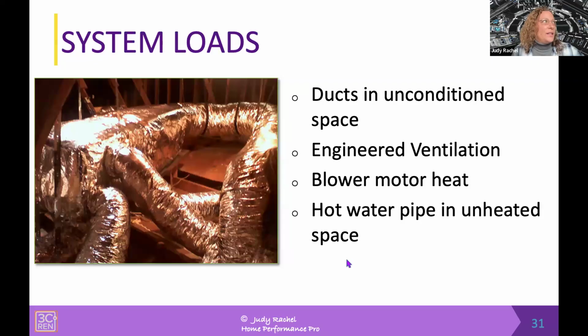There's also some other loads. There are what's called overall system loads. So we need to know a number of things about ducts when they're in the unconditioned space. We need to know about mechanical engineered ventilation. So that's continuous ventilation, not intermittent ventilation. This isn't the bath fan that can just be turned on and off. It is the bath fan if it's set for continuous operation. It's definitely not the kitchen exhaust hood, right? This is for the continuous mechanical whole house ventilation.